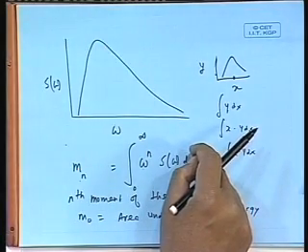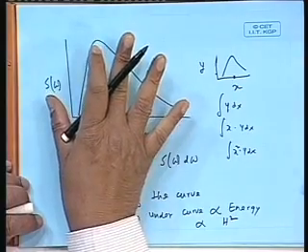And that energy is obviously proportional to the average height square or some statistical height square, because more energy means there will be higher waves, less energy means lower waves. They may not be one or two, but there will be random waves. So average wave height or significant wave height would increase if there is more energy. We will find out later that this M0 is directly connected to various kinds of wave heights. Let me concentrate right now on this part.